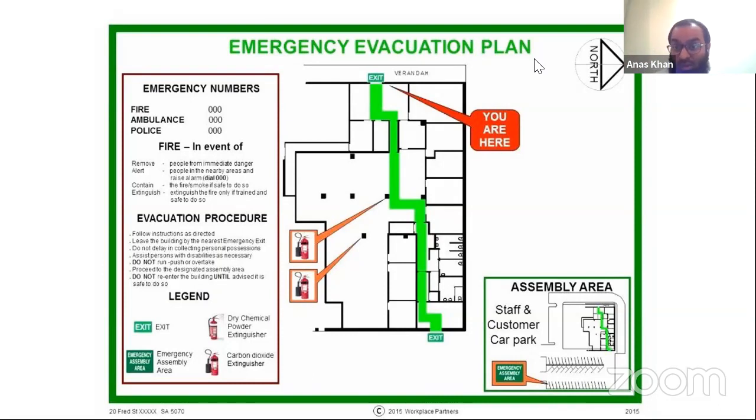And apart from these things, we need to raise awareness again and again. Every quarter, make it part of your training program to provide awareness on emergency evacuation and how to act in different emergencies. Maybe one time make a drill for fire, a second time a drill for chemical handling, a third time a drill for gas leakage, one time a drill for an electrical safety emergency, then a drill for a crane.